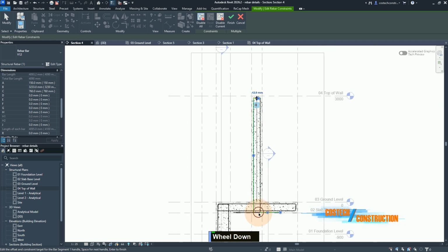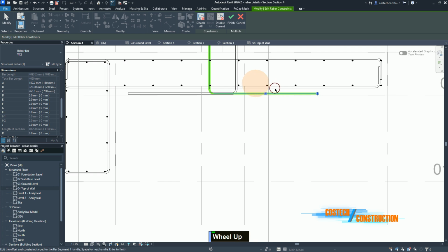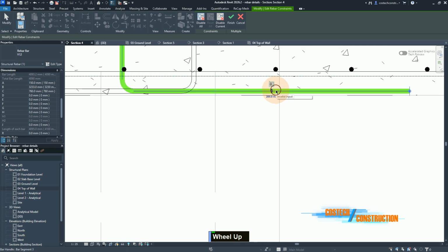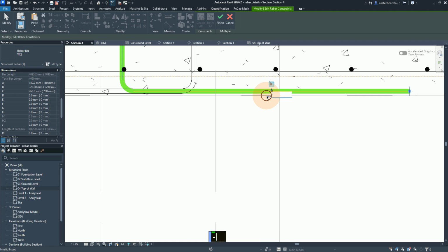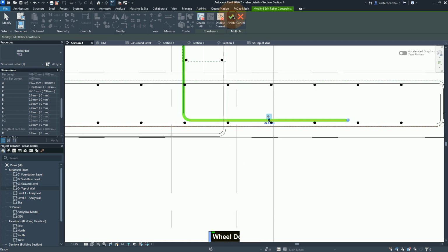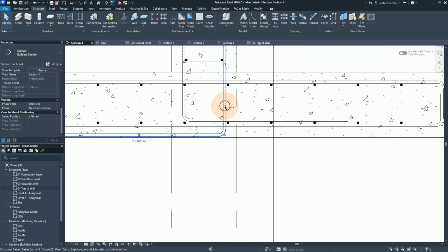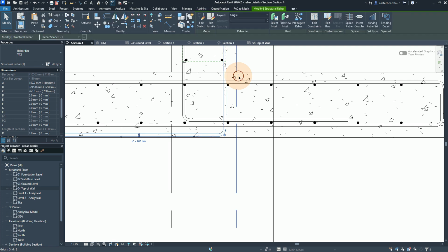You can go to the lower side. Now we can select this handle, then we select this cover, and now we give a value of -24. We can hit finish. We can select this other Rebar Set, then go to edit constraints.